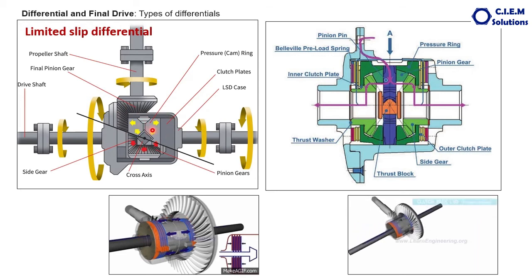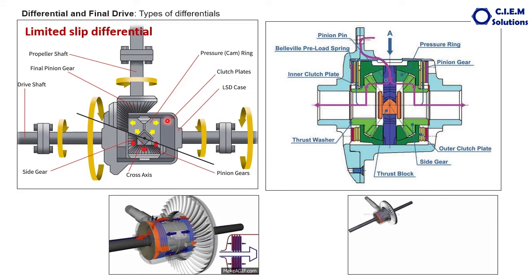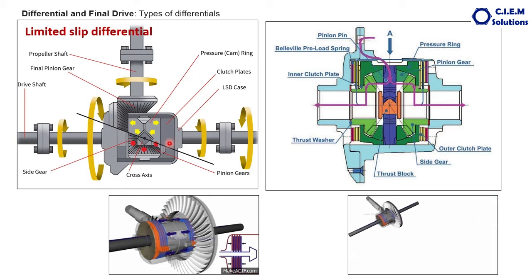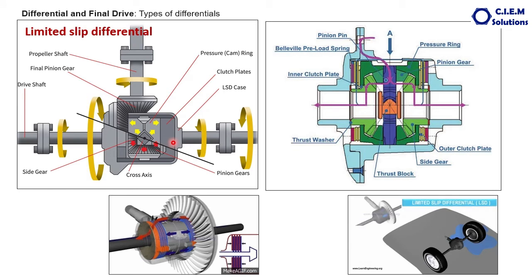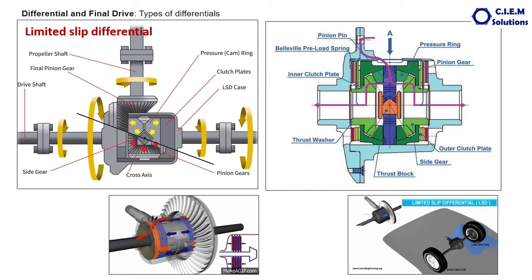So there is no differential speed for that particular movement. Then slowly the power is transmitted to the wheel which has the traction. The movement of these clutch packs depends on the amount of slippage. While this has this kind of advantage, it also has a small disadvantage. As time progresses, after some time the clutch packs get worn out. When the clutch pack gets worn out, slippage of the drive takes place, again losing its efficiency. This is how a limited slip differential works.